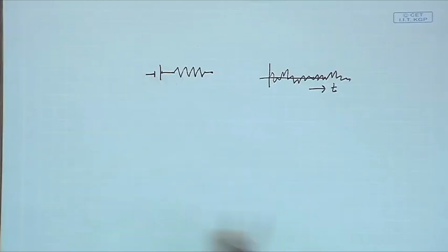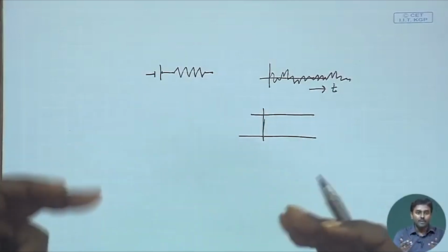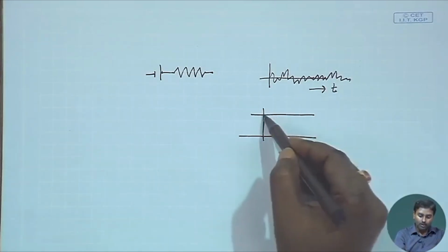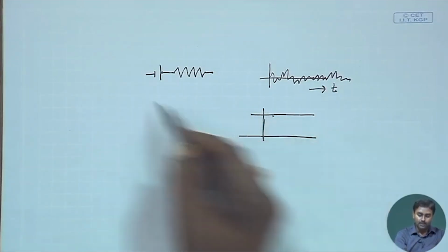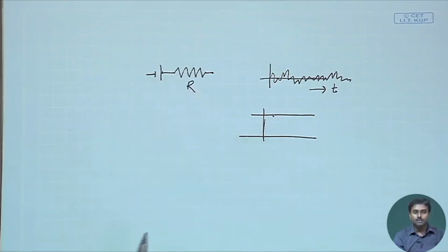Okay. Now if you start giving a voltage source across this, what will happen? Due to that voltage source, there will be a constant current across the resistance. Immediately you will see a DC shift to this random current. This DC shift will be due to the voltage source and the value of the resistance, from which you can calculate the current using Ohm's law.